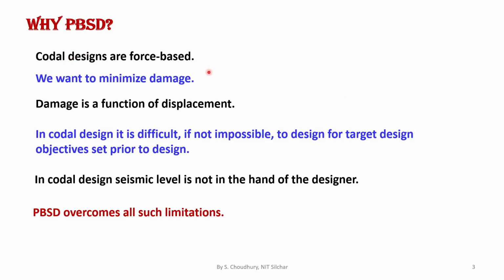Now, seismic codes are available for almost all the countries, saving one or two small countries, and mostly we are still following the codal design procedures. But gradually a shift is being seen now, as some countries are shifting to performance-based design. For example, in the American ASCE 41-17 code, performance-based seismic designs have been incorporated more or less. Similarly, in some countries it is available. So the future design world will be performance-based, and the present design world is gradually shifting to PBSD.